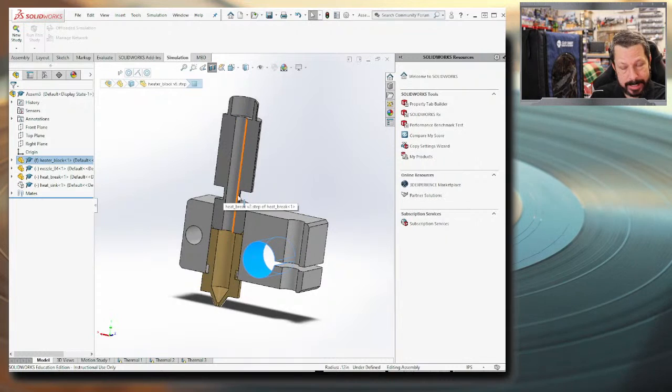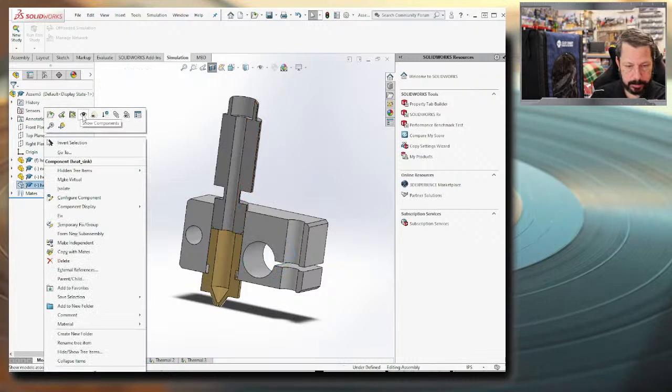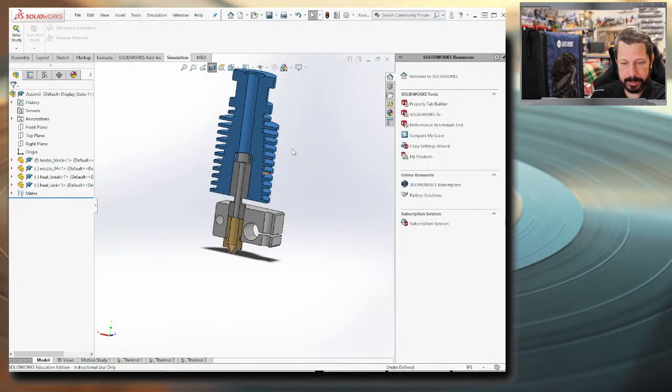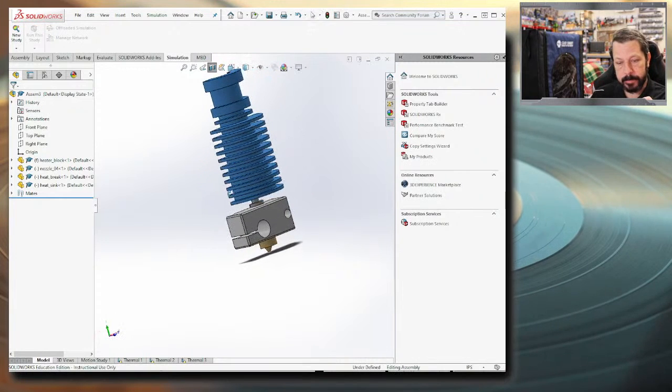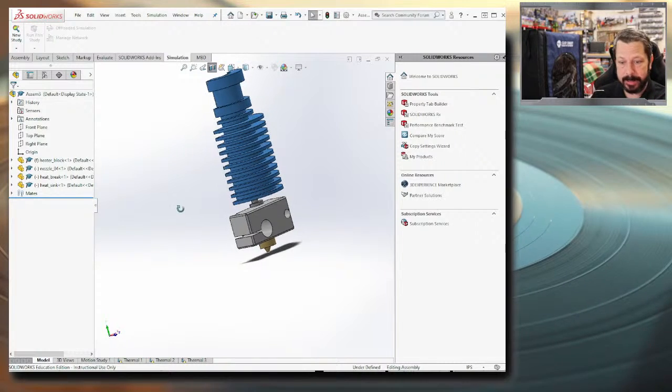There's a little bit of radiation. This block is 200 degrees basically, and there's going to be a little bit of radiation there, but surrounding all of this is our heat sink, this big giant, compared to every other part here, aluminum heat sink with a fan blowing across it. So it is conducting heat away as fast as it can.